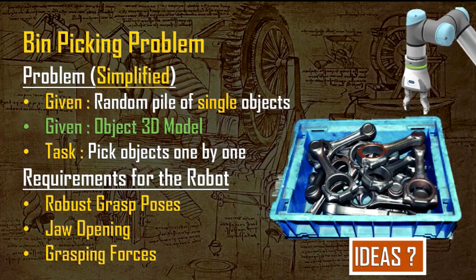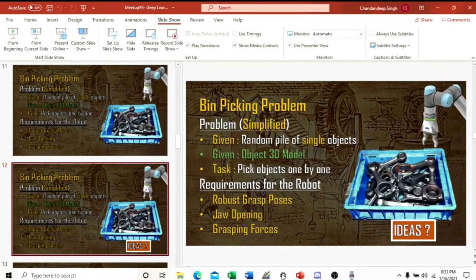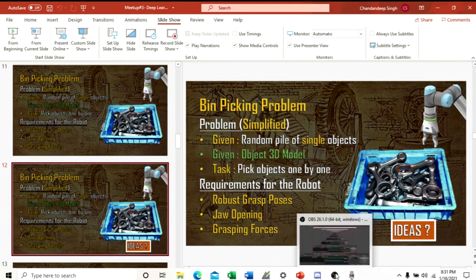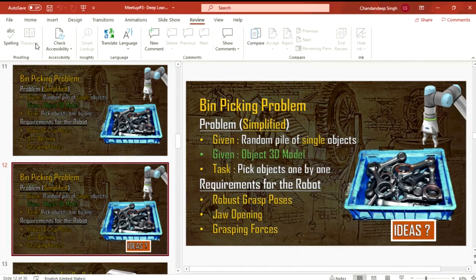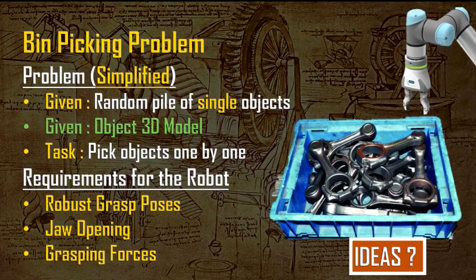The transformation matrices and the complete forward kinematics will be calculated, and the object location in the 3D world is identified from the camera and given to the robotic system. The transformation from the object location to the end effector position is calculated on the fly. Then the robot will be able to pick up the objects even as you go deeper.